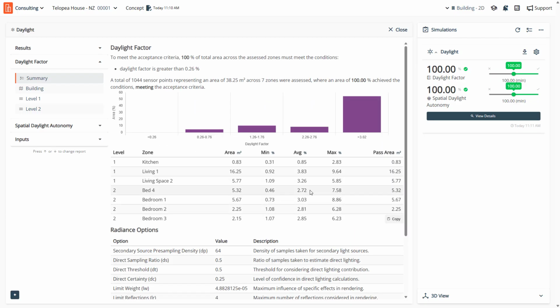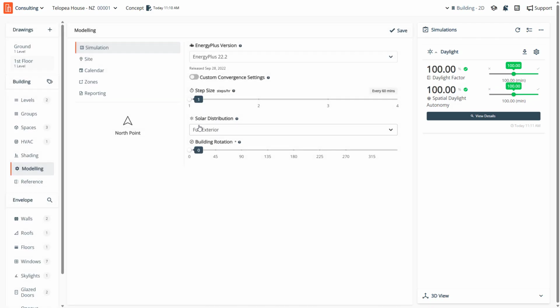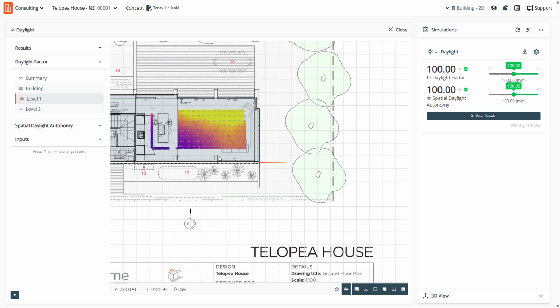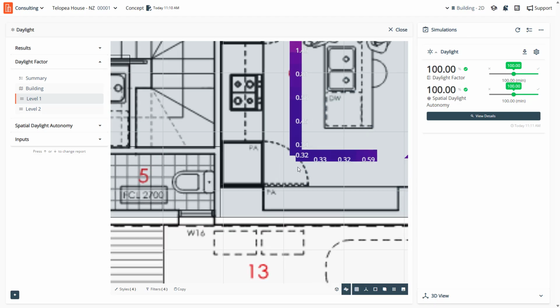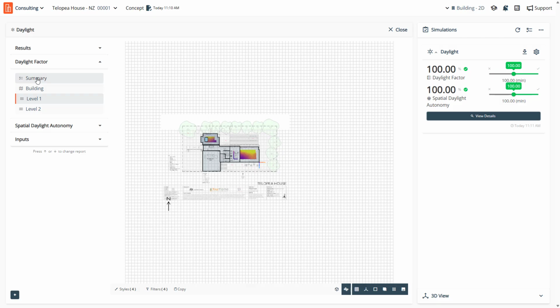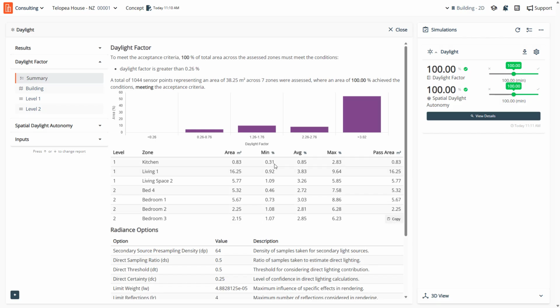Arguably the daylight factor is probably the easiest one for people to see in terms of minimum values. So we had a minimum value of 0.26 for Auckland. It's 0.31 there. So you can see it's actually not that far from the minimum value, and that minimum value there is directly relating to that value that was on this grid here. So 0.32, 0.31, just there, that will be the minimum values there. Okay, so we can see that in the results. That makes sense. 0.31, there it is.